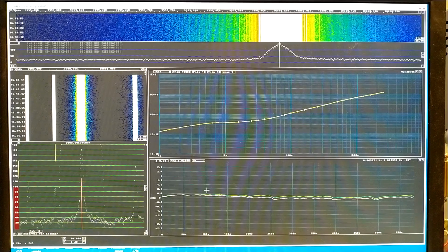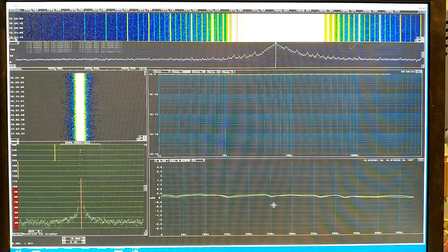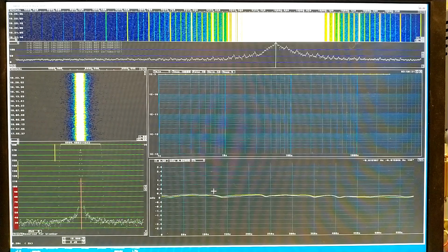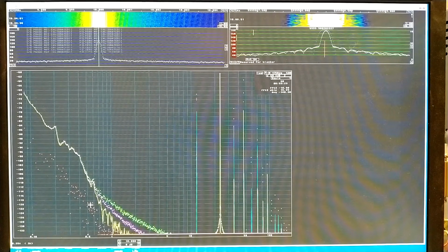This is now much faster than I showed before, half a second for each pixel. I have disconnected one column with 7 crystals, and what you see now is an oscillator with 14 crystals in parallel. And here is frequency versus time, and you can see a periodicity from here to here to here, and then it is more chaotic. The phase noise near the carrier is very high, and I can see also the spectrum. There is a lot of noise.